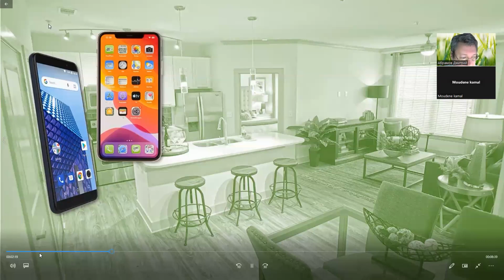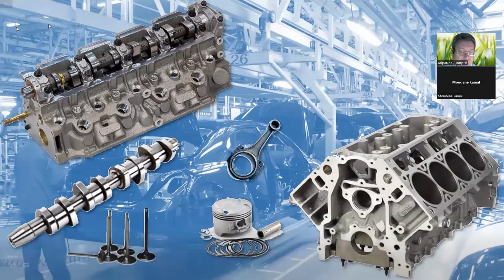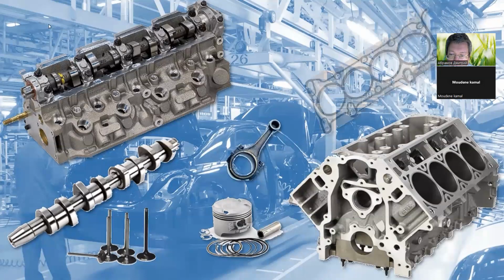Complex specifications. The surface of a cylinder bore must have crossed grooves to allow sufficient lubrication of the moving piston to avoid engine seizing. But these grooves must not be too deep, or they may potentially increase compression losses or lead to excessive consumption of fuel and oil. The cylinder head gasket ensures sealing both by its form and its chemical composition, but also by its surface texture and by the surface texture of the opposite sides which are in contact with the cylinder head and the engine block.